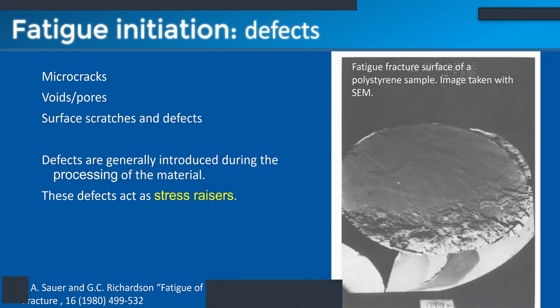Well, because if the tensile stress is too high, then it'll go plastic, and fatigue failure does not apply for plastic. It only applies for elastic. When it says elastic, you mean before yield stress. Yes. So we should always be operating, when we're using a medical device or any kind of material, under the yield stress of the material, unless for some reason you want your material to deform for the application.